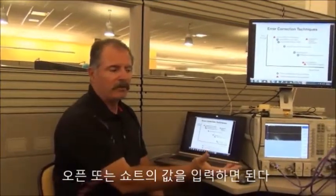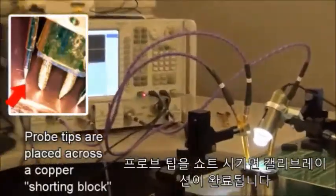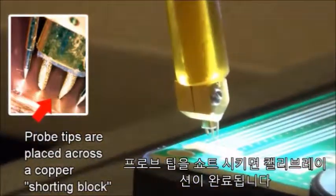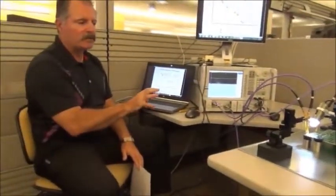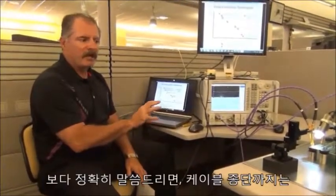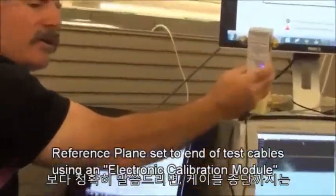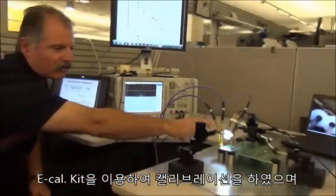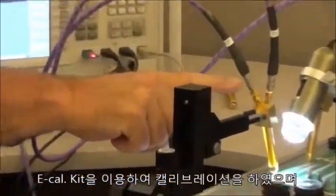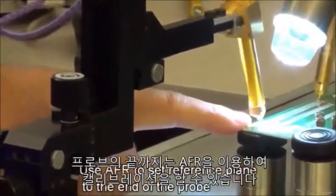So for example, in our system here, we've got probes. We want the reference plane to be at the probe tip. So all we have to do is put a short or an open at the probe tip, and that's the calibration. So to be more specific, what we've done here with this system, we've done first an SOLT with an ecal. So we've done a short open load through to the end of the test cables. So we've got a coaxial environment with SOLT. But what we really want is the reference plane down here at the end of the probe tip.